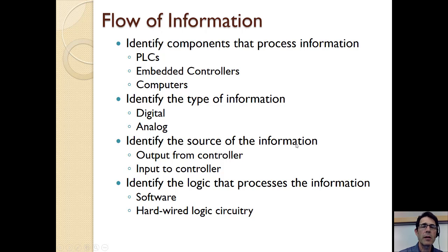All right, so that's just another way of looking at a system. And so as we go through the course and look at various systems, we're going to be analyzing it in this way. We're going to be looking at how does energy flow through the system? Why is that actuator not moving? And where's the path of energy to that, and what's interrupting that? Or is it a matter of information? Maybe all the energy and the relays, everything's in place, but it's just not getting the information from the controller. So that's another part of troubleshooting.